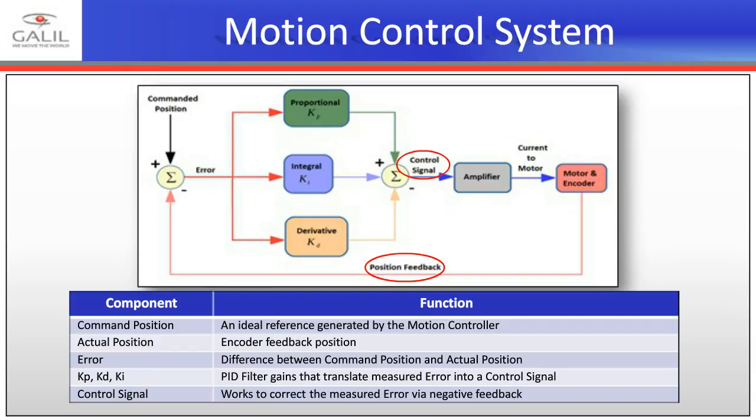Downsides: analog signals are susceptible to noise. Even digital encoder signals can fall victim to noise in extreme cases. There are ways to mitigate this: cable shielding, differential signals, but analog signals will always be susceptible to some sort of noise. Wiring between multiple components leads to an increased risk of failure and grounding concerns.